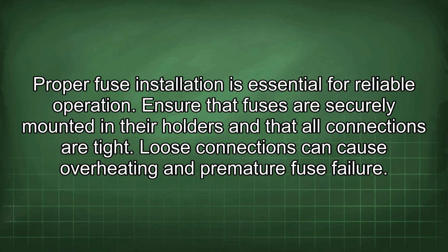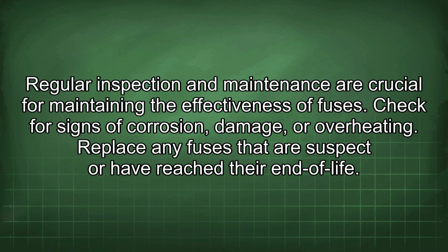Proper fuse installation is essential for reliable operation. Ensure that fuses are securely mounted in their holders and that all connections are tight. Loose connections can cause overheating and premature fuse failure. Regular inspection and maintenance are crucial for maintaining the effectiveness of fuses. Check for signs of corrosion, damage, or overheating. Replace any fuses that are suspect or have reached their end of life.